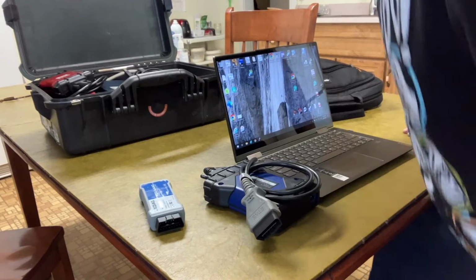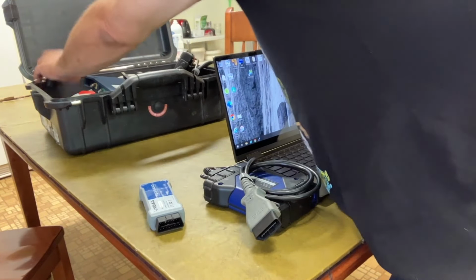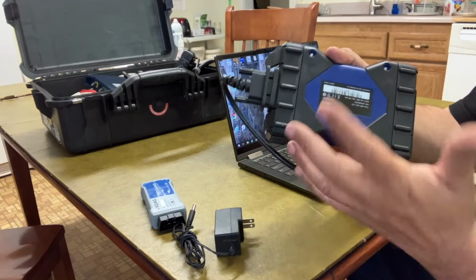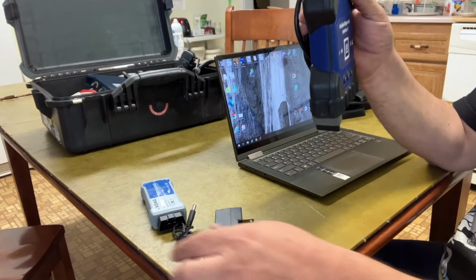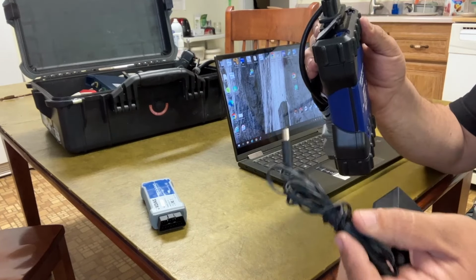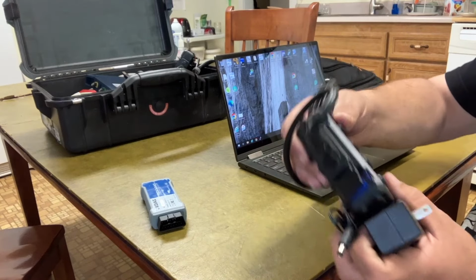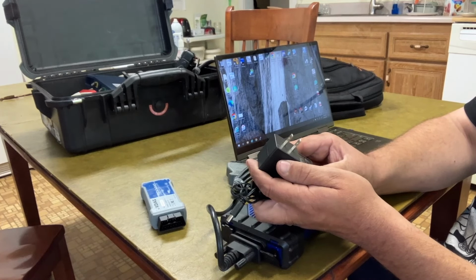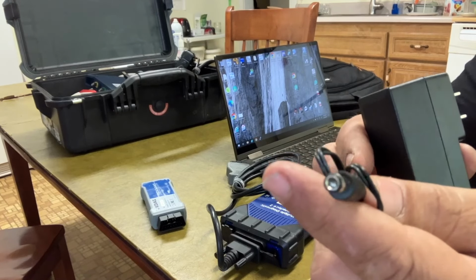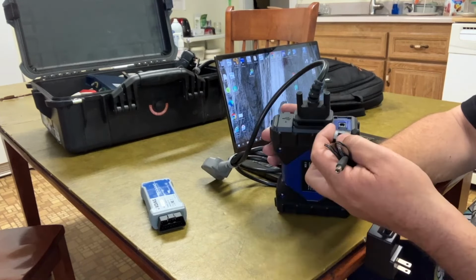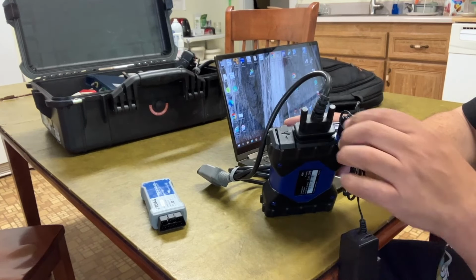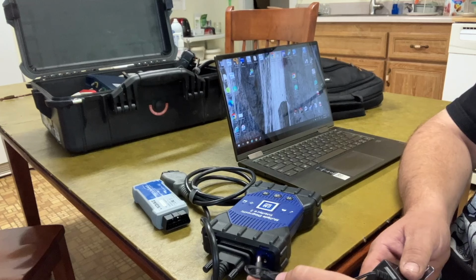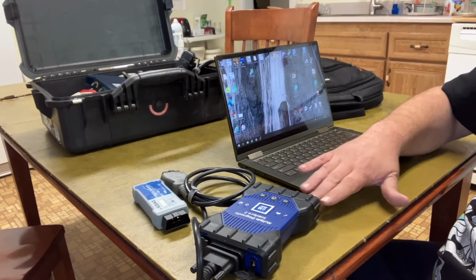The other thing about these is the real ones have a spot where you can put batteries in the bottom. I don't have that. So when I program, I run this AC adapter. It can be anywhere like 5 to 30 volts or something. This is a 9 volt off of something that I had. It puts out 0.3 amps, 9 volts, and it's positive in the center of that jack, and it fits in here. It's just an old one that I had laying around from something else, and I decided to use it. It will power when you plug it into the OBD. It'll power when you plug this in. This does not power from the USB at all.